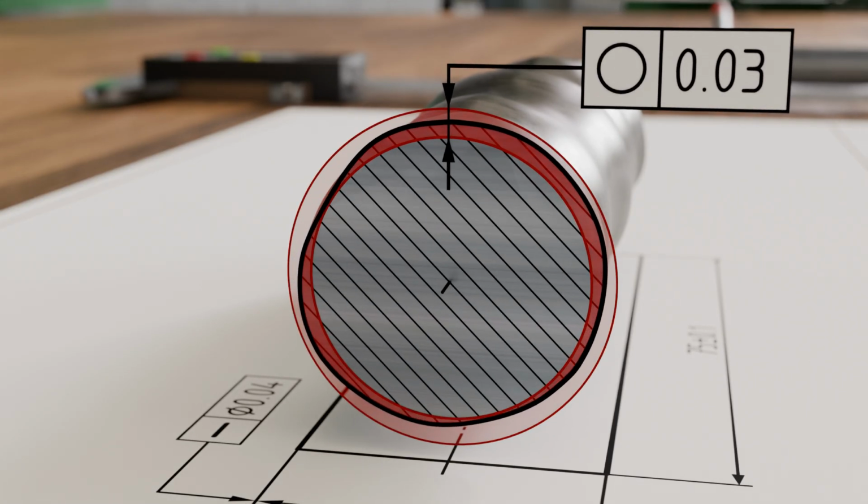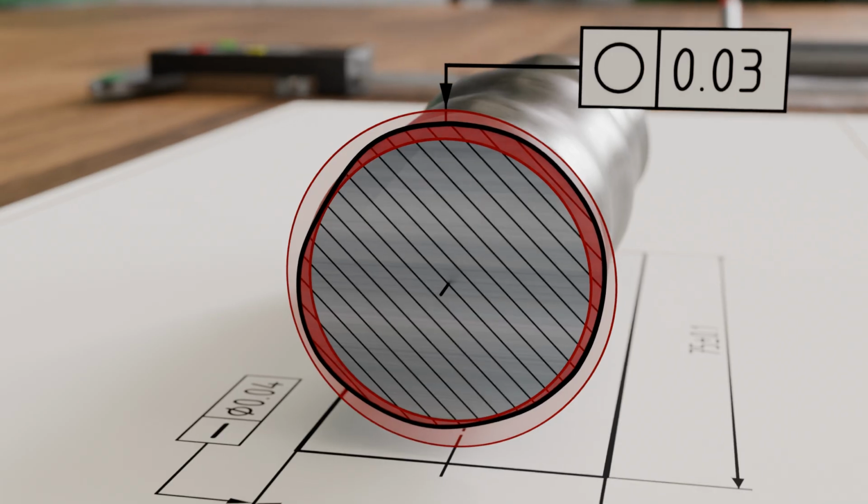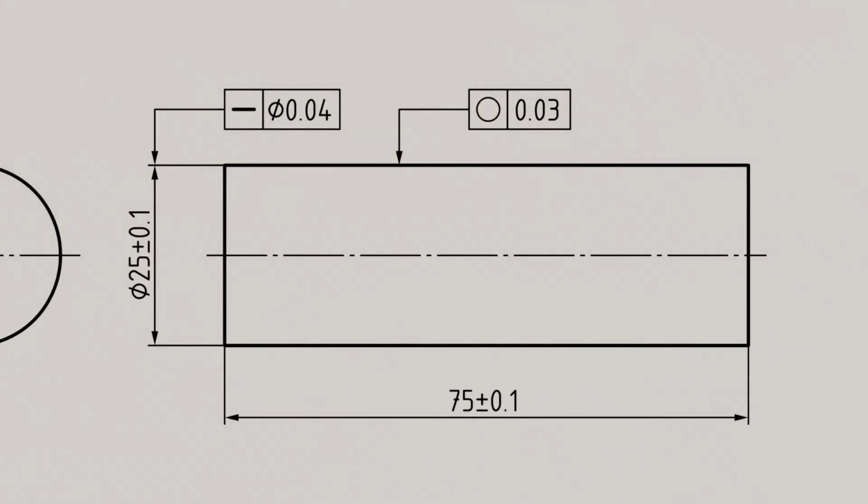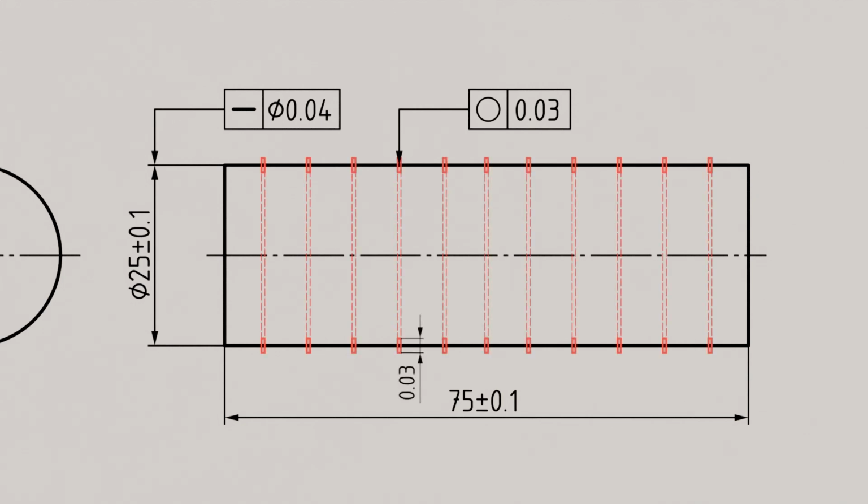If the actual geometry lies entirely within this annular tolerance zone, the shaft is considered round. To specify the roundness tolerance, the form tolerance arrow is placed on the corresponding surface. The roundness then applies to every imagined cross-section along the relevant axis. In the illustrated case, the roundness applies along the entire length of the shaft.